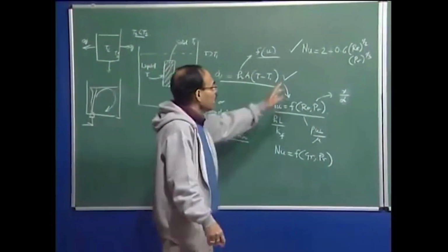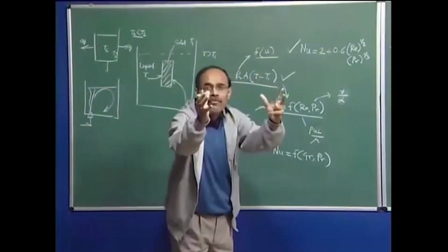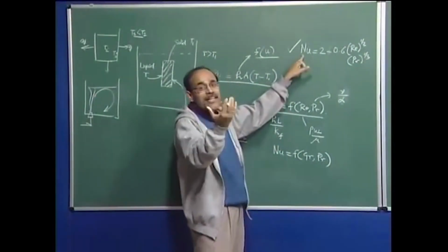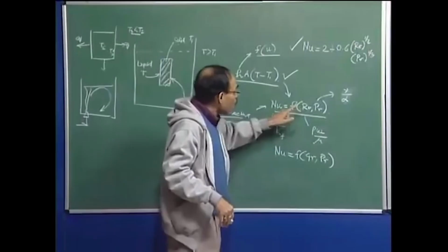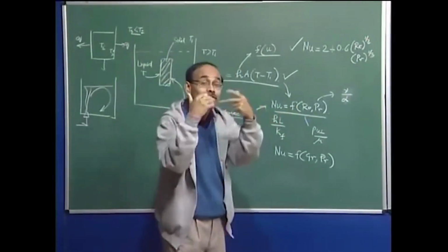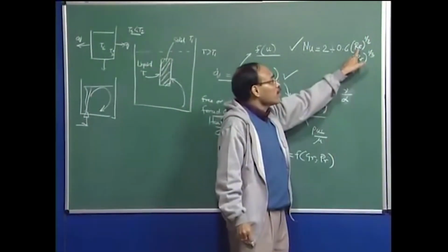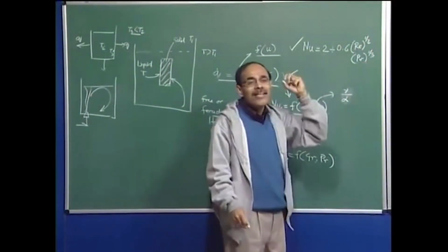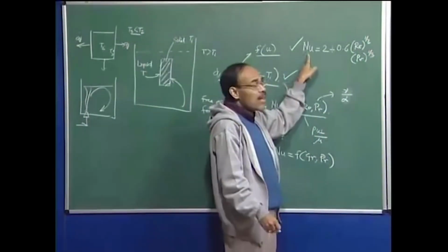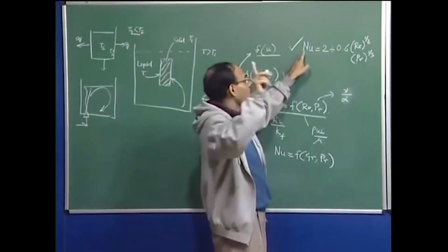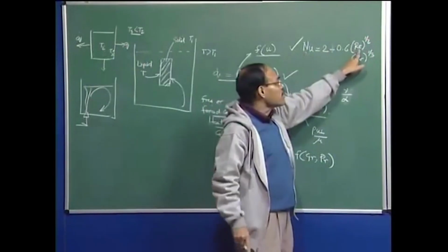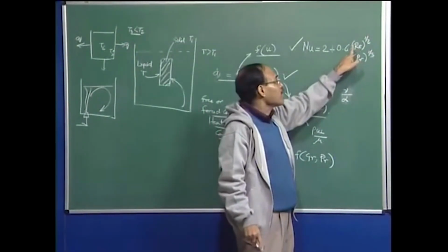So, therefore, assuming that a forced convection correlation is available, next would be to find out what is a meaningful velocity scale that we have to use in that particular correlation. So, in this correlation, the moment I say that the velocity in the Reynolds number is known to me, it becomes a trivial exercise, because on the left hand side now there is only one unknown, and that unknown is the heat transfer coefficient. So, having obtained some information on the flow, I can calculate Reynolds number.